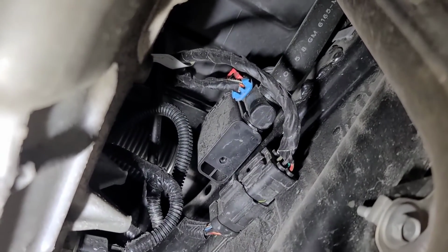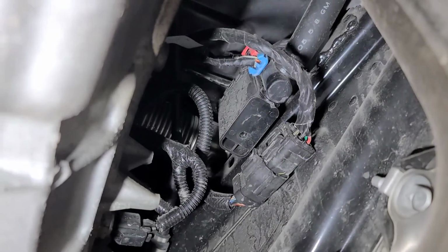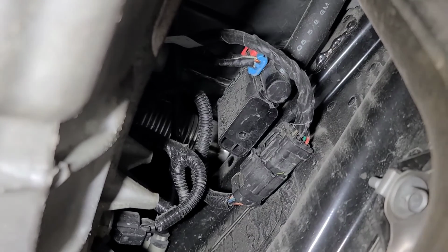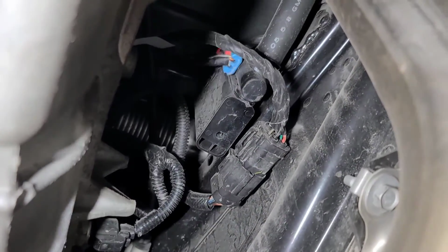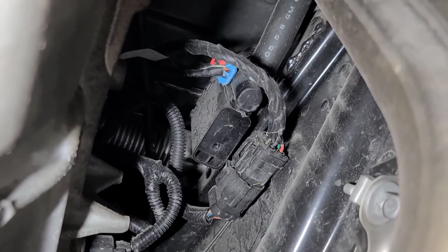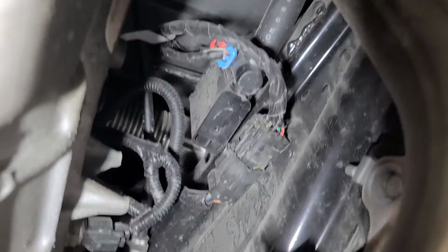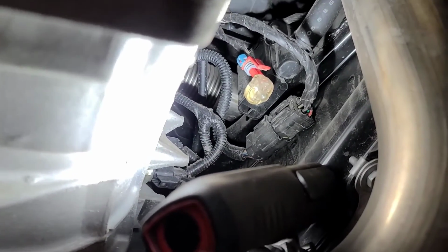It looks the same as the ones on the trucks. So we're going to unplug that connector and connect the test light across the connector. One wire should be power with the key on, and the other wire is ground side controlled by the ECM. But rather than checking all that, I'm just going to put a Noid light across the wires or connector and see if I can command it on. So there's a Noid light installed. It won't come on until it's commanded on, so I'm going to use the scan tool now to command it on.